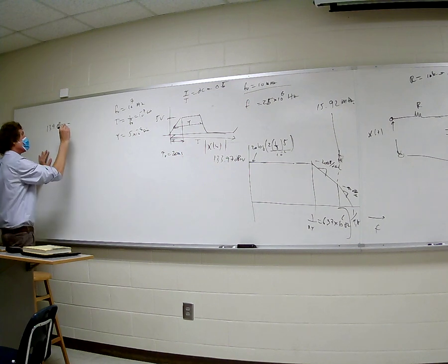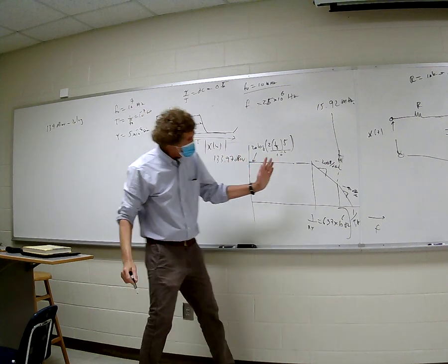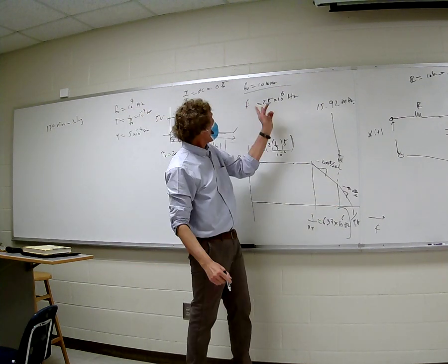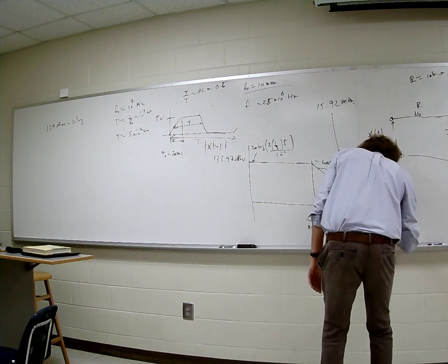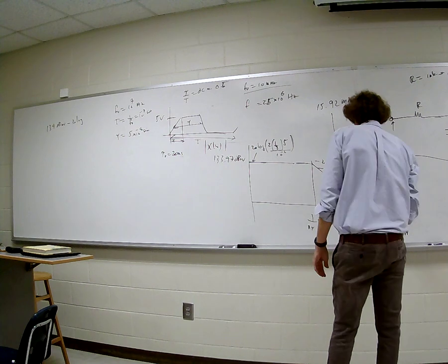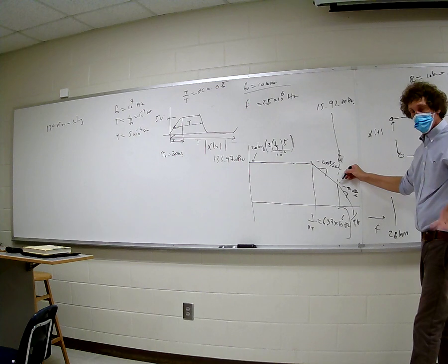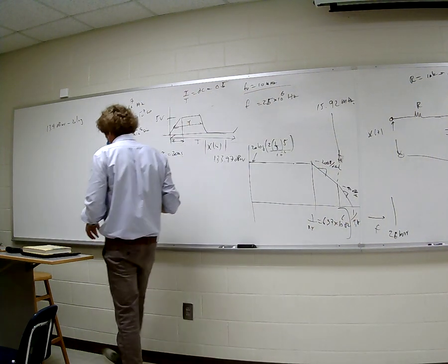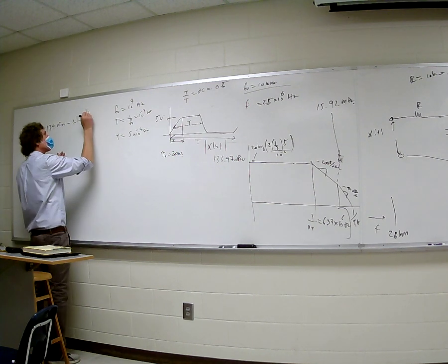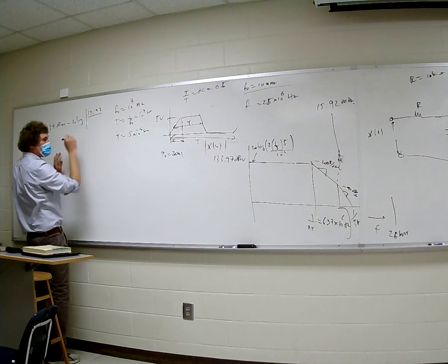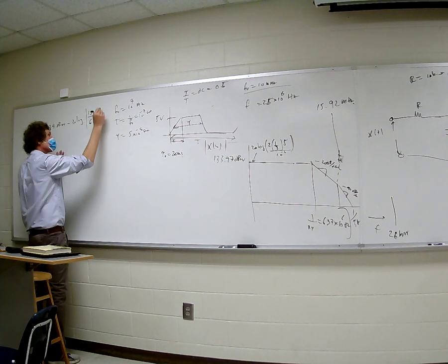Minus what? Now take a look. 20 times the log of what? Well, the frequency I wanted, I put 25 megahertz, is way out here, right? 25 megahertz is here. So I know I'm going to go through this region where it's dropping at 20 dB per decade. You all with me? So how much did it drop? Well, I have to take the upper frequency it stopped at, which is 15.92 megahertz, and divide it by the frequency it started at, which is 6.32. Isn't it, William? Yes. All right.